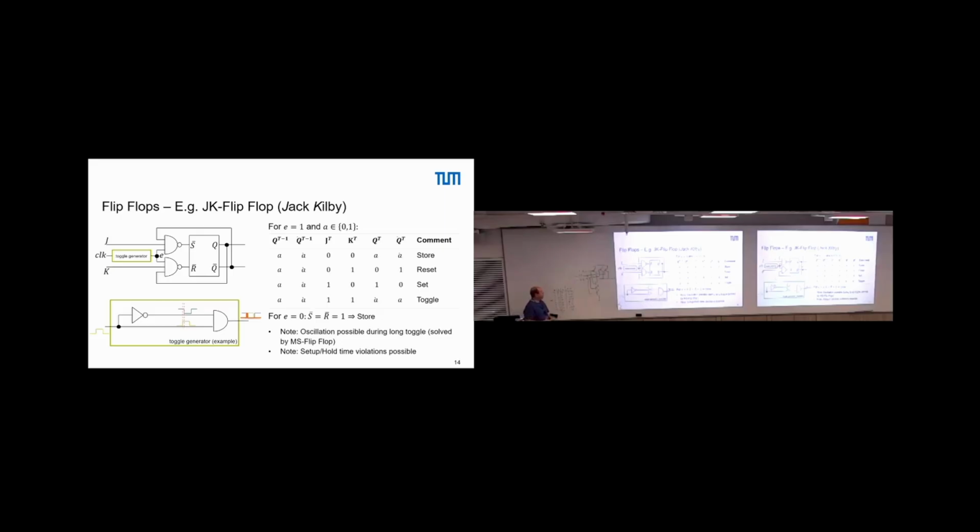Now, what would you do if you want to build a NAND with 4 inputs, 5 inputs, 6 inputs? You do the same again. That works up to a certain extent. At some point, since even if they are on, they have some resistance, this will no longer work without scaling up massively the transistors and so on and so forth.